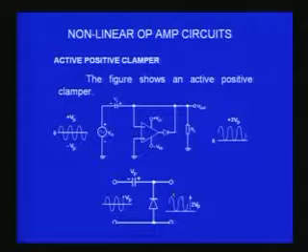Now what I get will be a clamped sine wave. How this comes about I also explained to you in the previous case. When the input goes negative, then this diode can be forward biased. This is ground, this is going both positive and negative as the signal goes, and therefore when it goes negative you find the diode is forward biased, and therefore the diode will start conducting.